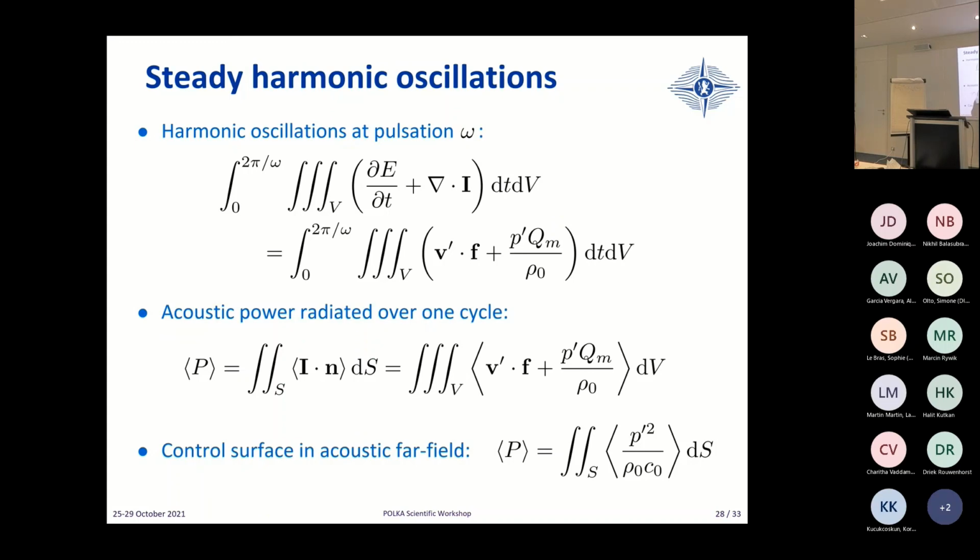But if you put it here, what is happening in here? In the pipe, you have a maximum of pressure fluctuations, but what about the monopole itself? You have a node of velocity, because in this scenario where the air is breathing in and out, this is always a stagnation point. So you have no chance to modulate the heat transfer if you place the grid in the middle. You must first have a source, and you make sure that you have a source by placing the grid at a location where you have some acoustic velocity and effectively modulate the amount of heat transfer.